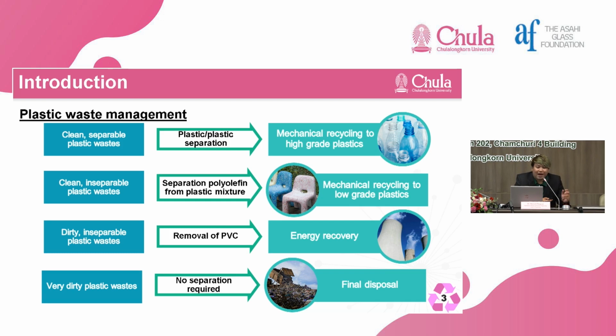So plastic separation is needed. However, it's quite difficult. Sometimes only the easy separation is used, like the sink-float separation to recover the floating plastics, like the polyolefins, PP (polypropylene) or PE (polyethylene), from others, and then we can make material of lower grade. But the others mostly go through the incinerator for thermal treatment or energy recovery.